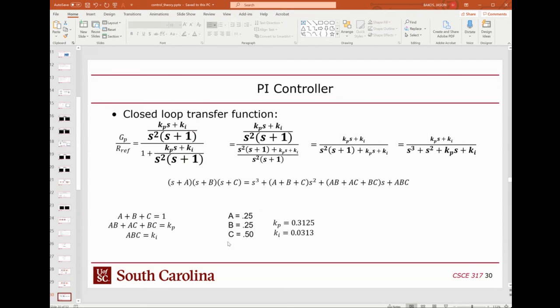In this case, it turns out that it's an underdefined system. Underdefined? Yeah, underdefined. We have more variables than equations, right? So we tried to pick values that would stabilize the system, and also we wanted to pick them so our poles would be in the left-hand plane. So really, what we're doing is pole placement. This is one strategy for building controllers, is pole placement.